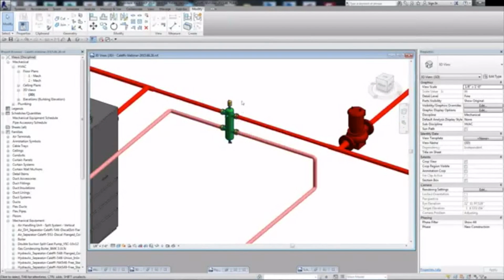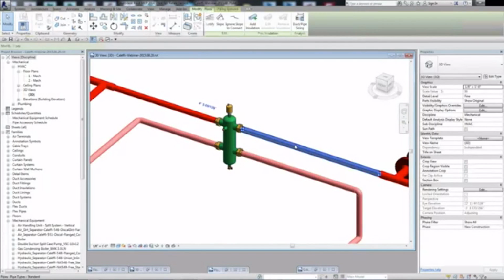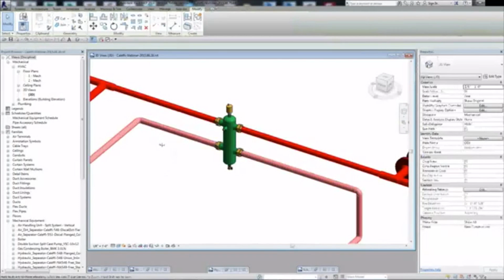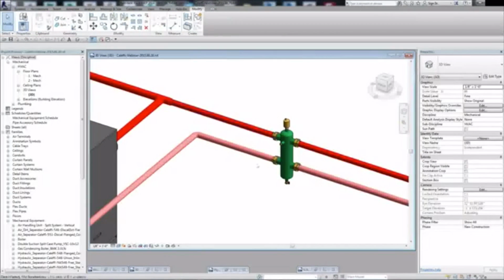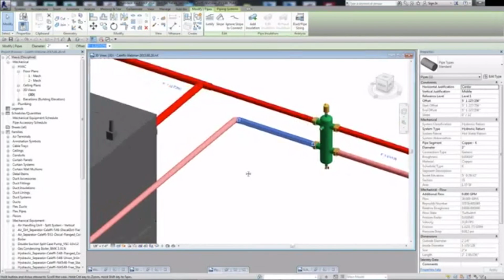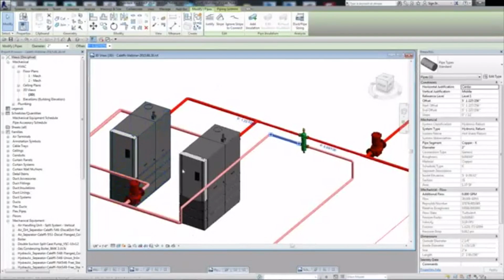So what we have within the Revit content for Caleffi is the ability to separate the systems. In this case, we already talked about the distribution side, the secondary side, being 8 GPM, and from supply and return, it's set to 8 GPM. But the supply side could be something totally different. In this case, I have it set to 30, and the return is also set to 30. And those are also factors determined by the end system, the end system units being the boilers.